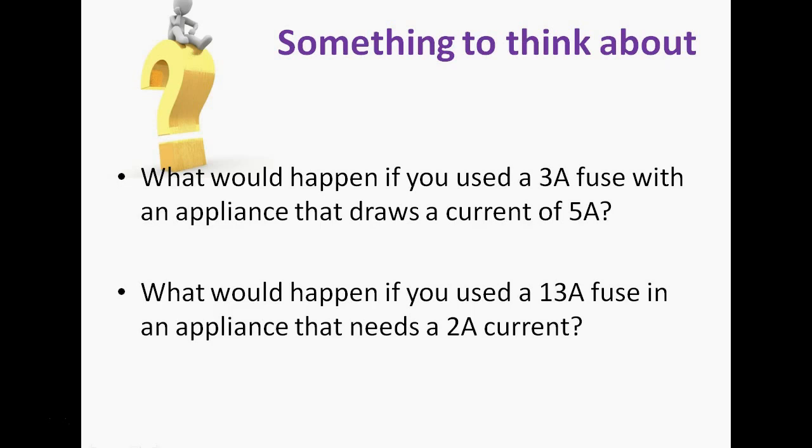In the second case, if you use a fuse that's way too high, then the current could go dangerously high, much above the operating current actually needed, and cause overheating long before the fuse melted. So that's why it's really important for safety reasons to make sure that you don't use a fuse that's too high, and obviously if you want your device to work, you don't want to use a fuse that is rated too low.